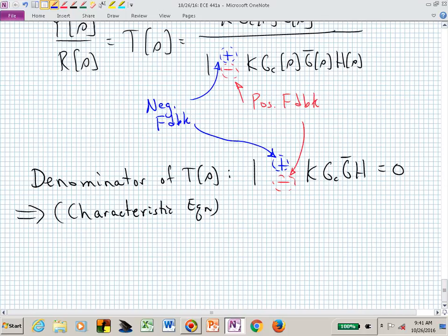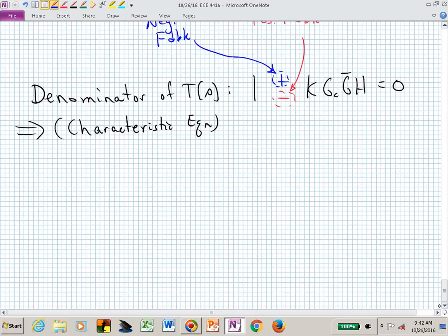And you can derive that from the block diagram algebra. You know where those signs are arising from or how they're coming into play. And we typically have negative feedback, so we use the blue and we have 1 plus K G sub C G bar H. We are going to, in this class, actually focus on the negative feedback, because if we did the positive feedback, we would have 2 sets of rules. There's no reason to be that confusing in discussing the root locus. Let's just focus on always having negative feedback, and then we can establish these rules. But bear in mind, if somebody now says, oh, your phase angle condition is different, well, then they're probably talking maybe about positive feedback. But we will deal with negative feedback and focus our attention that way.